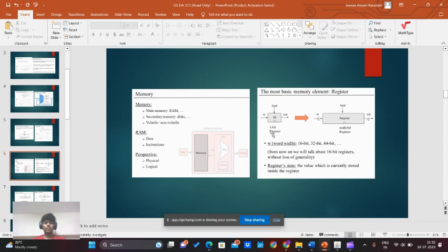The RAM unit is composed of a sequence of addressable registers where each register stores a 16-bit value. The registers can be read by probing the output, which reflects the current state of the register. To write a new value, the input is set to the desired value and the load bit is asserted. This causes the register to store the new value and start emitting the updated value from the next cycle onward.